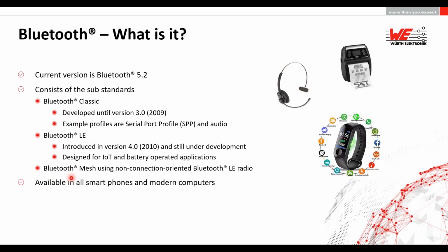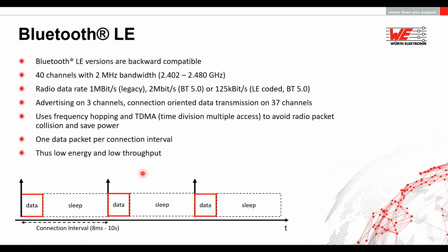And a recent development with Bluetooth has been the Bluetooth mesh. It itself is listed as a variant, although it is a standard on its own. So more on this a little bit later. Let's concentrate on Bluetooth Low Energy, because this is the real interesting thing for our remote control and monitoring industrial application. So Bluetooth Low Energy, as you already know, works in the 2.4 gigahertz band.